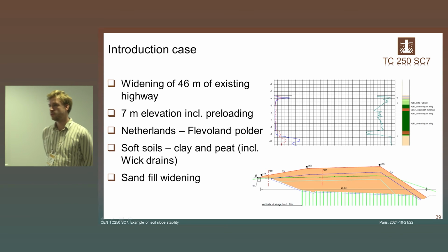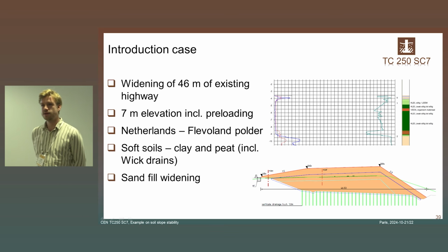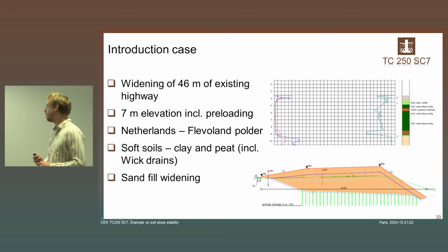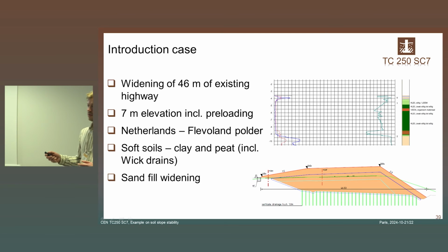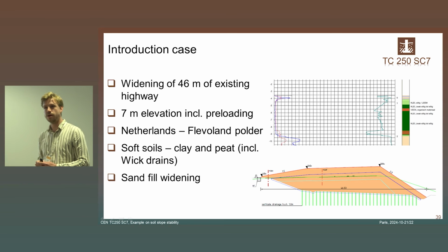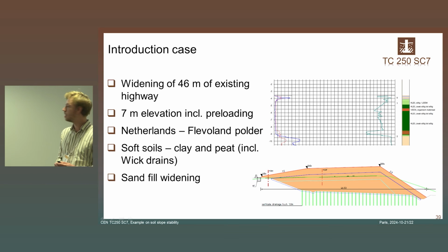Overheight was used to accelerate the consolidation process together with the wick drains that were used. And applying this widening and sand fills is exactly where the slope stability analysis comes into play on these soft soils, because with every step or every meter that was heightened, the weight of this sand is directly transferred to the pore pressures in the soft soils, and in turn decreases the strength of the soil.